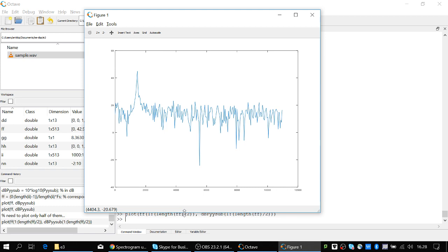Okay, so this actually tells me I have a noise level around 18 dB, maybe somewhere here. White noise, spectrally very dull, and then it has this one peak at around 1500 Hertz or something like that. You can get better values by some graphic tools here.